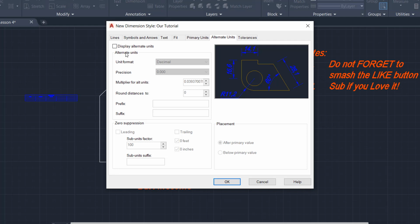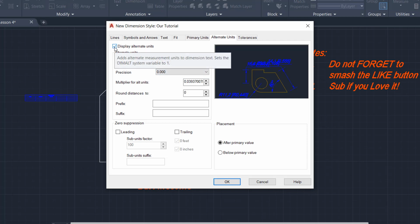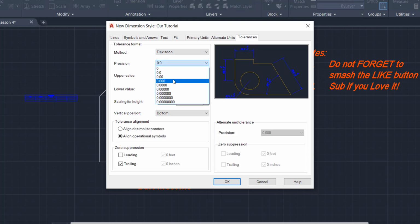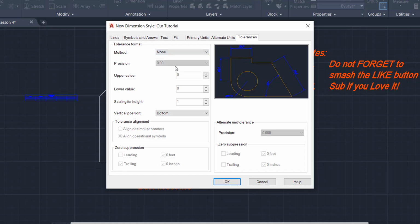Alternate units will show another unit format near the main one. All settings are same as primary units. Normally, you don't want to display alternate units unless you work in an international project or something like that where you will have two unit types. Tolerances are needed if you are on metalworking or product design. You might need a method where you have got a deviations of plus or minus 5 millimeters. We don't need that also. 2 hours later. That's all for dimension style.